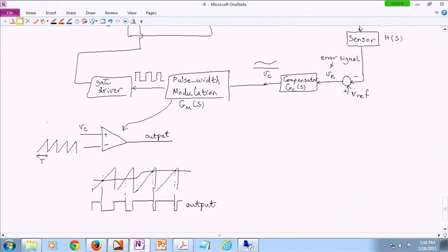So we are talking about how we are generating this sawtooth waveform. You have a capacitor and a switch, which is basically a transistor. You are charging this capacitor with a constant current source, which is a current mirror in microelectronics. When I open the switch, the voltage rises. When I close it, it goes down to zero and then goes up and down. So the question is, the average current of this capacitor should be zero, right? How is that possible? Here is how.